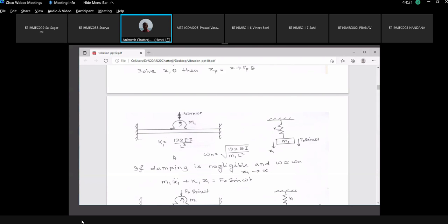Induction motor RPM is close to synchronous speed divided by integer n. Synchronous speed is line frequency speed. In India, the line frequency is 50 hertz. In America, line frequency is 60 hertz. But in India, 50 hertz. So 50 hertz corresponds to 3000 RPM. In India, all the turbines and generators, all power producing generators, must rotate at 3000 RPM because the line frequency is 50 hertz.